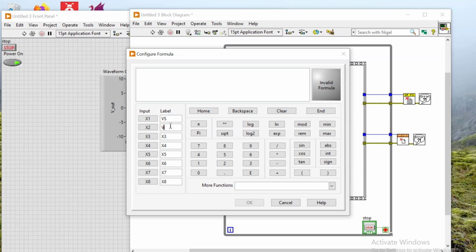The output voltage, we'll say V0. And we need R1, right? That's the resistor that we pick to go with our thermistor. And so those are the three variables. And then I don't have R2 here because that's going to be the output from here.